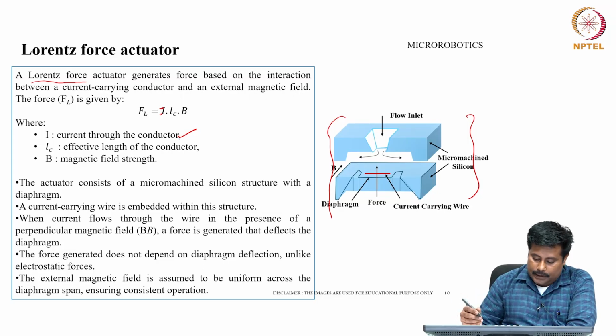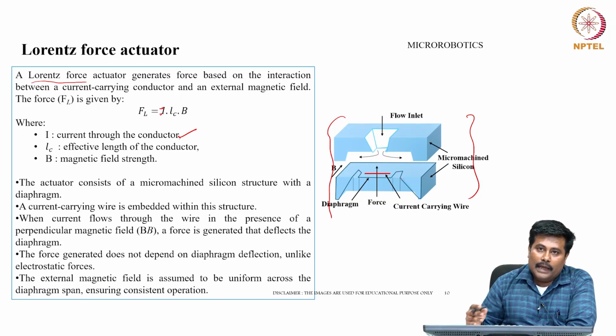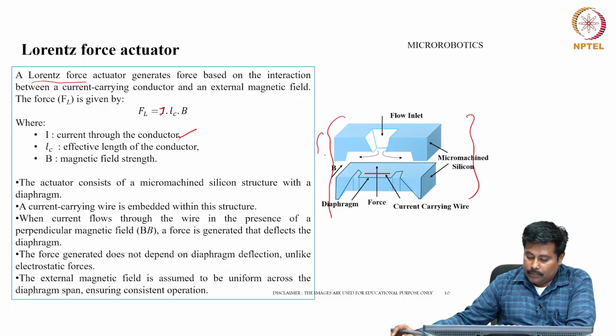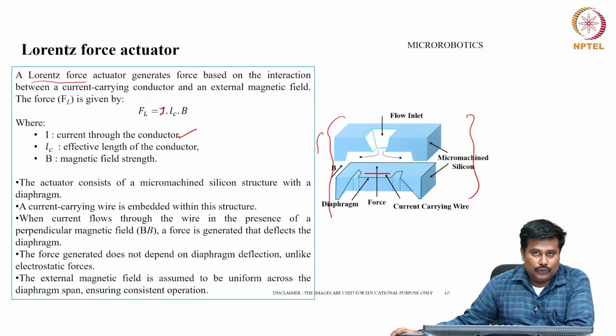The force generated does not depend on diaphragm deflection, unlike the electrostatic forces. The external magnetic field is assumed to be uniform across the diaphragm span, ensuring a consistent operation in this particular system. So, ideally these are some kind of generalized Lorentz force actuators which are being used.